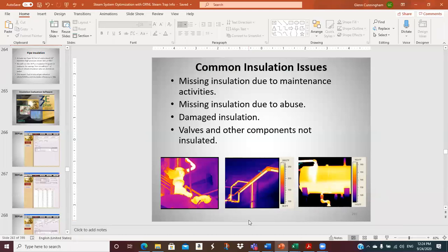Okay. Well, the capacity of this boiler is what? 250,000 pounds an hour, right? So if you're making 175 divided by 250, you're running at 70% load. So if you're at 70% load, you probably need on the order of 70% of the rated capacity of the fan, right? It would make sense because the fan has to be big enough to operate at 250,000 pounds, or you got screwed when you bought the boiler. They didn't sell you a big enough fan.